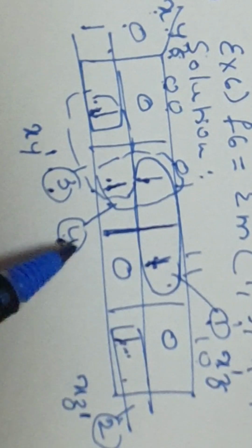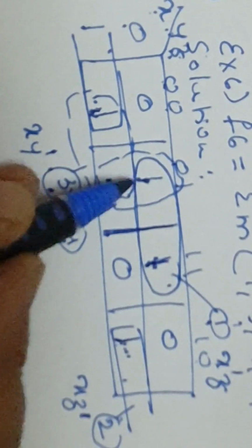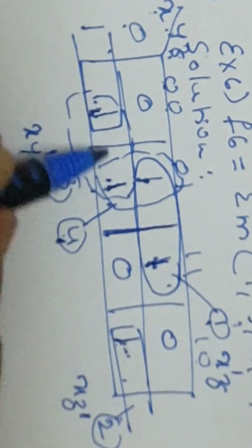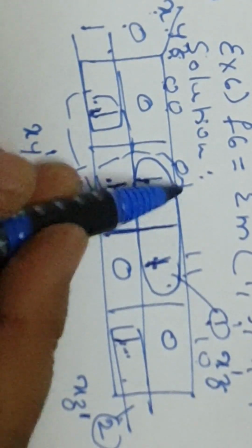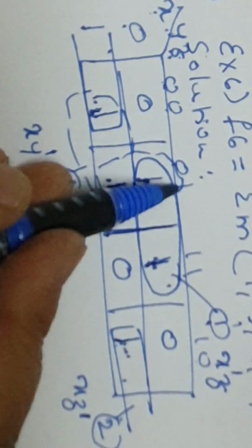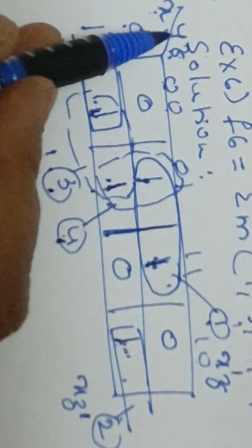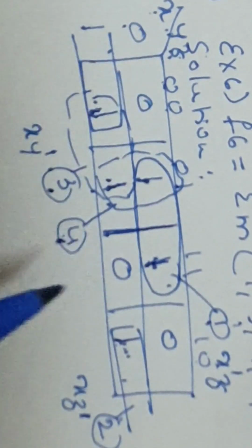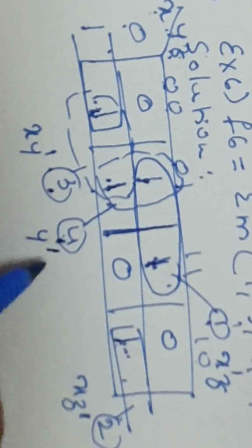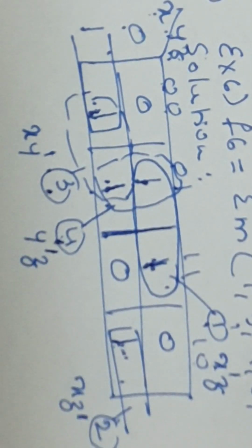Now the fourth one, if you take this group, two ones, this row and this row, x is 0, x is 1, row wise nothing is common, leave it. These two ones fall in a single column, 0 1 is common, 0 corresponds to y, that is y dash, 1 corresponds to z, that is z, so y dash z, right?